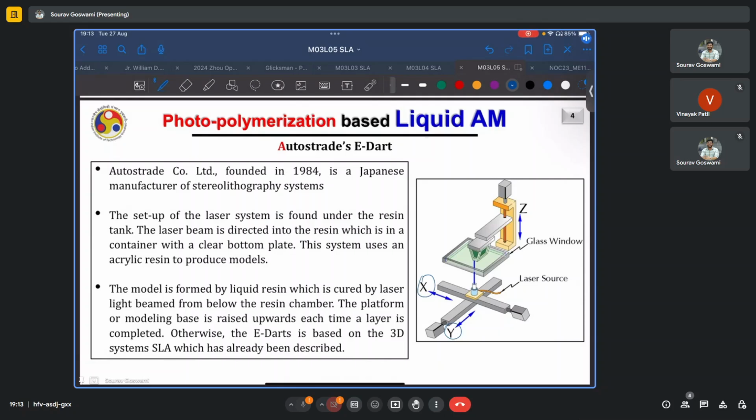Now, the advantage in this case would be that because the vat of liquid is not moving, there will be little to no instabilities or surface perturbations, which might be induced due to inertia effects from the motion of the vat. However, on the flip side, as we are well aware, the laser optics are actually the most fragile part of any, say, laser processing system. And in this case, the laser optics itself is being moved or traversed along the XY directions. Thus, this process is very slow as you cannot really move the laser and the optics at high speeds to cover the region of interest. We must move at very low speeds.